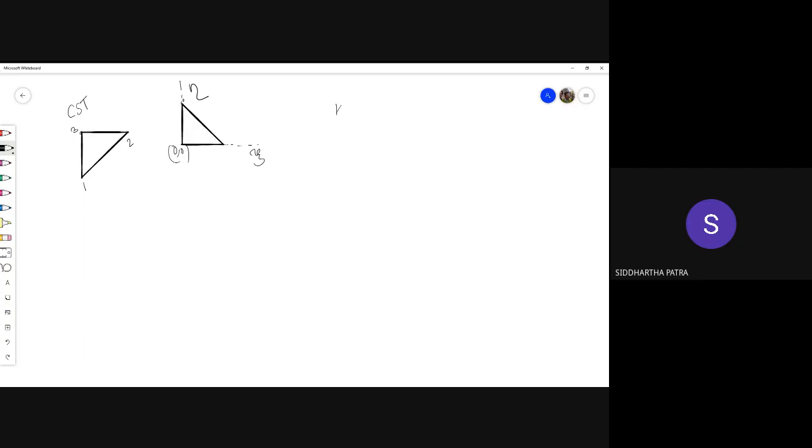the element stiffness matrix, and other matrices and vectors, are defined like this. That is a general representation for the stiffness matrix: B transpose D bar B. All of these are different matrices times d omega. What is omega? Omega is basically differential volume. So this thing is omega in the interior, and the boundary is called gamma.